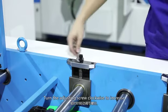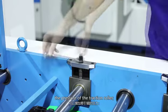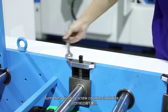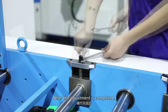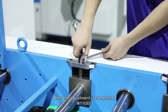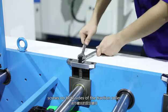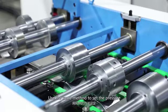Turn the adjusting screw clockwise to increase the pressure of the traction roller. Turn the adjusting screw counterclockwise to reduce the pressure of the traction roller. After the adjustment is completed, tighten the fixing nuts of the adjustment screws on both sides of the traction roller. Use the same method to set the pressure of the remaining traction rollers.